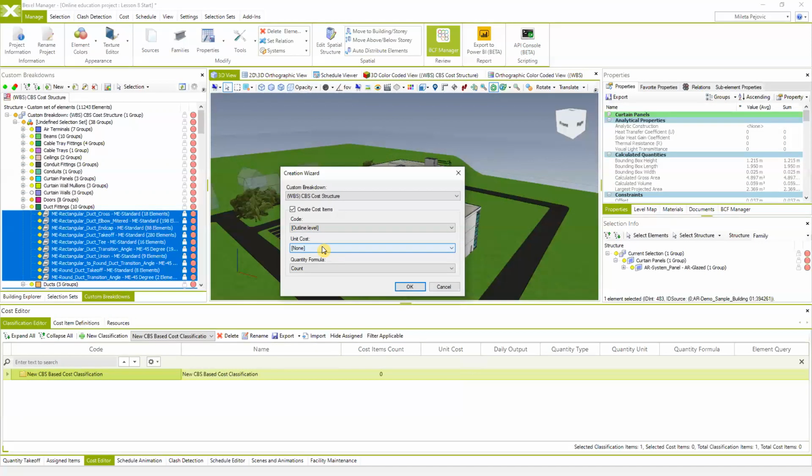The next option is unit cost. Similarly, as you can add or populate specific metadata in your BIM elements, such as codes, attributes, properties, whatever you're using for specific segregation purposes of your BIM project, or just to populate the metadata which is requested by the client, you can also include the price data. For each element in your project, using the authoring tool, you can add specific cost information.